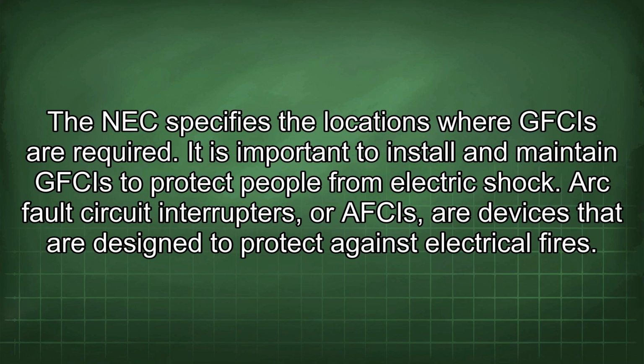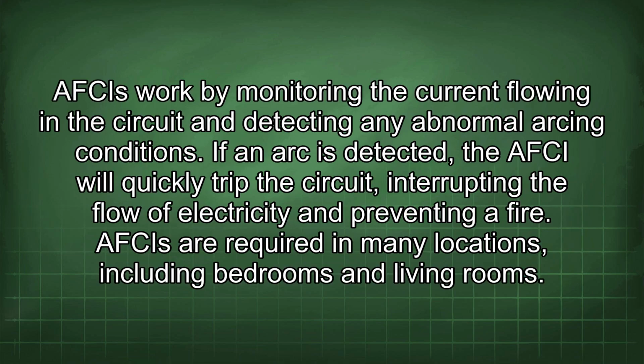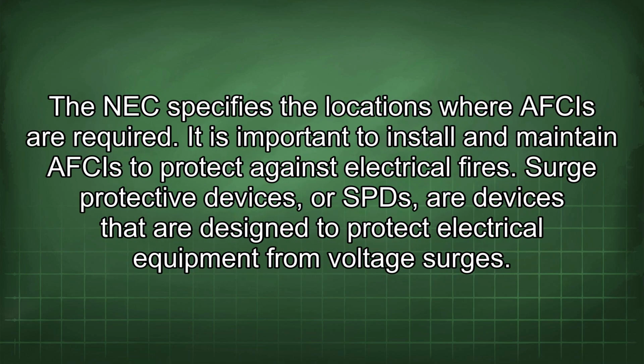Arc fault circuit interrupters, or AFCIs, are devices that are designed to protect against electrical fires. AFCIs work by monitoring the current flowing in the circuit and detecting any abnormal arcing conditions. If an arc is detected, the AFCI will quickly trip the circuit, interrupting the flow of electricity and preventing a fire. AFCIs are required in many locations, including bedrooms and living rooms. The NEC specifies the locations where AFCIs are required. It is important to install and maintain AFCIs to protect against electrical fires.